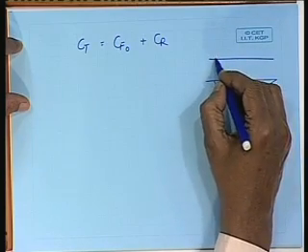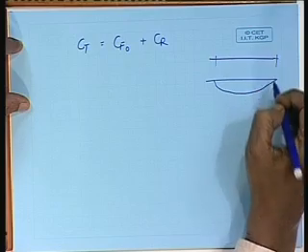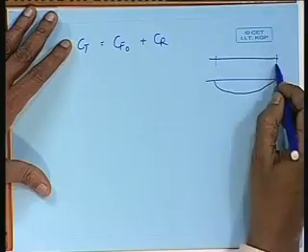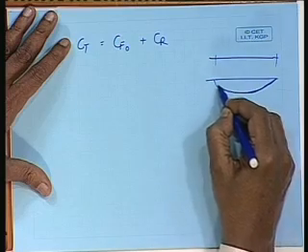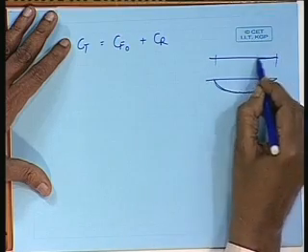If I take the same length, because Reynolds number is dependent on length, the Reynolds number of the flat plate and the ship is the same. For the same Reynolds number, if I take the same length, then the water has to travel this distance, whereas here the water was traveling only this distance. Is that right? So, therefore, there will be an addition to frictional resistance in 3 dimensions.